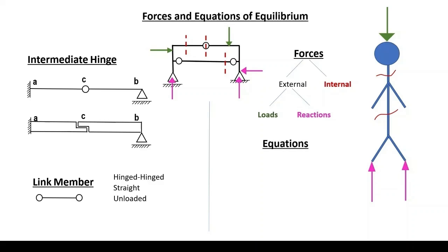Equations controlling the equilibrium of the beam. We have three equilibrium equations in plane. Sigma forces in the x direction equals 0, sigma forces in the y direction equals 0, and sigma moments at any point equals 0. Those three equations, each of them applies for the whole structure.